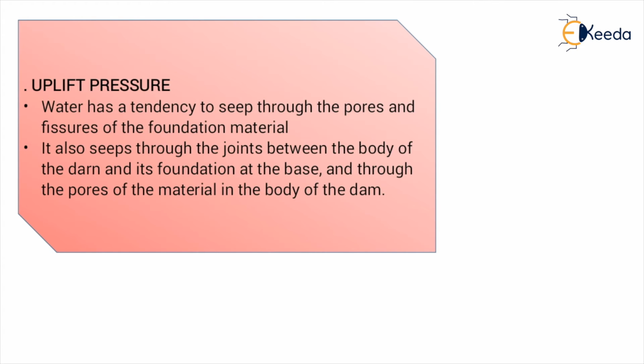So the water has a tendency to seep through these pores and fissures of the foundation material. It also seeps through the joints between the body of the dam and its foundation at the base, and through the pores of the material in the body of the dam. The seeping water exerts pressure, and it must be accounted for in the stability calculation.